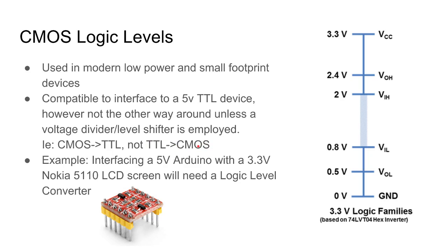Due to the nature that TTL runs at 5 volts, if you output the 5 volts to a CMOS device, there is a chance that you can damage the CMOS device, as the voltage will be out of spec and too high, and they're not designed to accept such high voltages. Luckily, there is a way around this. You find a lot of modules available online.